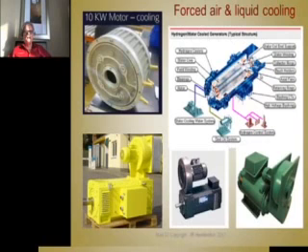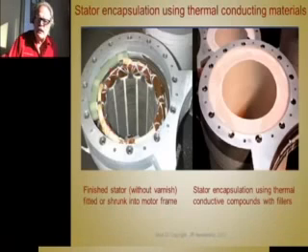Now here's an example of a very large machine with hydrogen coolers, stator core, field windings, bearings, rotor, high voltage bushings, and retaining rings, axial fans, brush holders, collector rings, stator winding, stator end ring support. This is probably the collector rings. This looks like a synchronous generator, stator cooling water system, seal oil system, hydrogen cooling system. Serious cooling required on big machines with long diffusion paths to get the heat out from the sources.